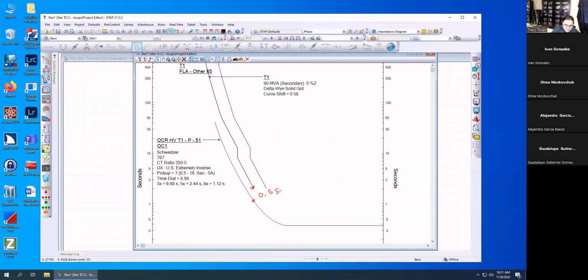For the class, I'll say 1 second just to give us a little more leeway, but half a second is perfectly fine. A little more, just for fun. So how can we tell the time exactly? Well, you have a fun button right here. This is your time delay. The way it works is you click it, get out of drawing mode, and notice you have this little arrow pointing up. You can select a specific curve, so let's select this transformer T1 curve right here.